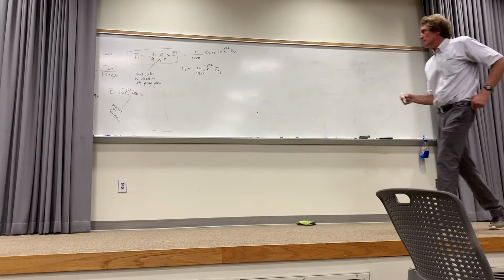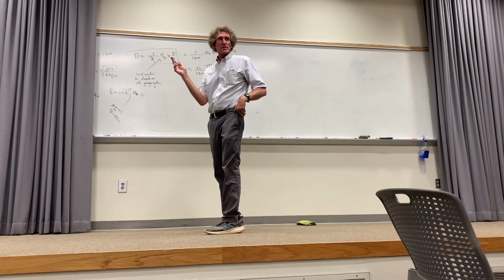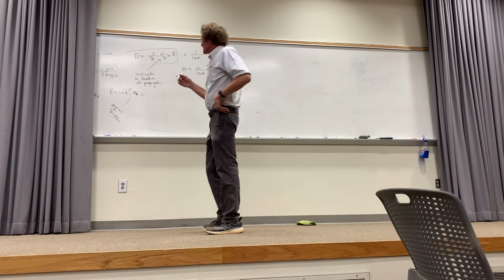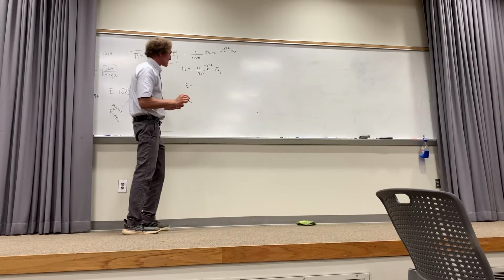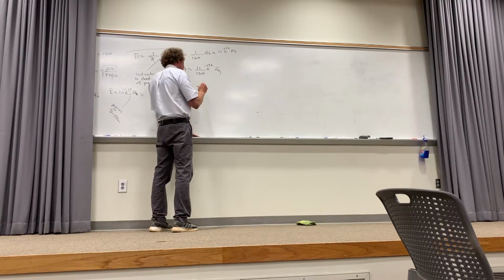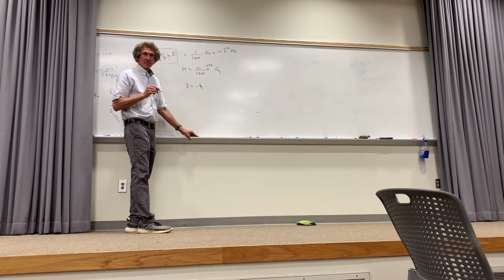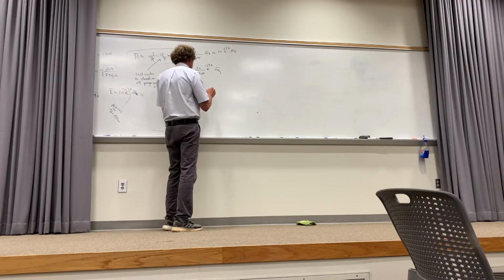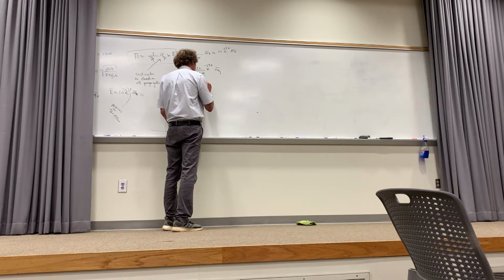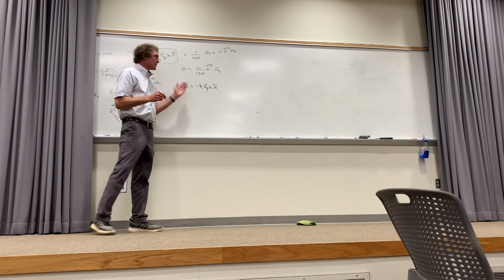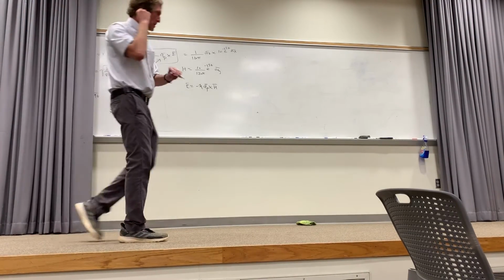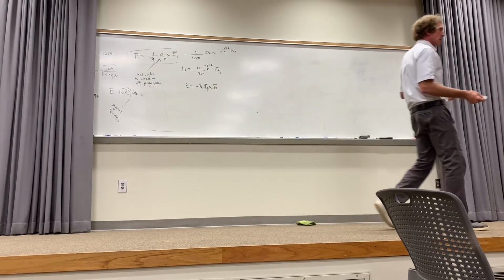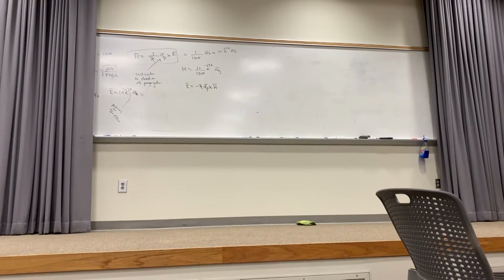Now there's a corresponding one to get the E field. Do you remember doing this with Dr. Wentworth or Dr. Riggs? You do? Okay. So when you get the E field, a simple way to get it for propagating fields is you put a minus sign down there, and then you put the intrinsic impedance here. Now it's multiplying, not dividing. And it's going to be times a_P, a unit vector in the direction of propagation, crossed into the H field. So if you're given the H field, you can get the E field, and given the E field, you get the H field. Are you with me? It's very straightforward, but you have to be aware of it. And you have to do problems with that to get good at it. And that way it sticks with you.